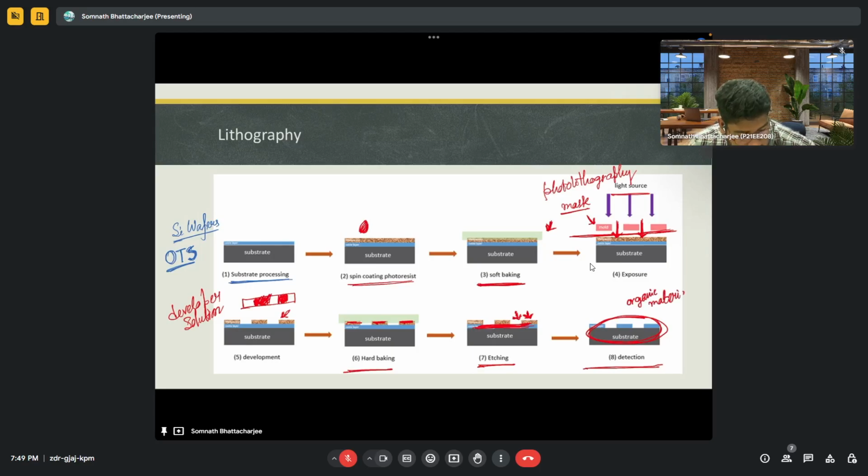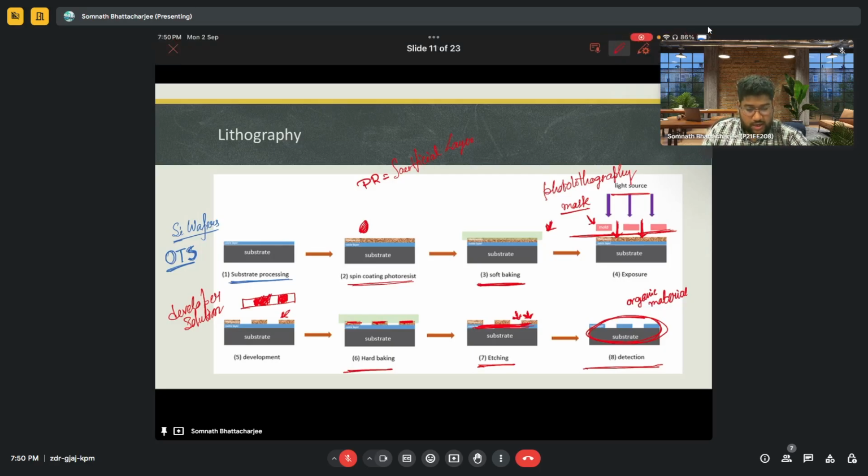So this structure of this PR is called the sacrificial layer, because it is anyway sacrificed. It is used to just create this kind of structure, a specific design, but it's sacrificed anyway. And apart from this, there's the design on top of your desired material, and you can just directly do this. And this is a very, very accurate technique, and you can get a very direct design directly on top of your material.